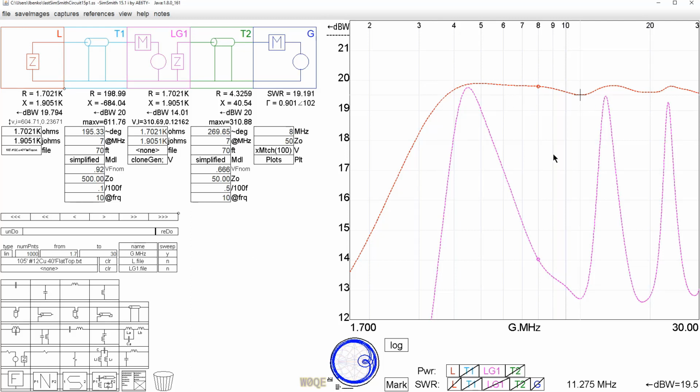So this is an incredible number of calculations going on here at the moment. But as long as we stay with the open wire line, our losses are low, everything's good, and we should be able to afford ourselves a pretty easy match to that smaller range of impedances. Let me wrap this up right now saying that the next video is going to be on the Johnson Matchbox.